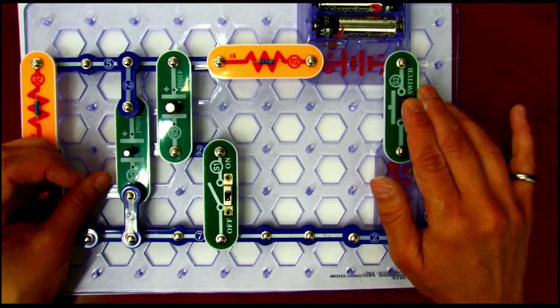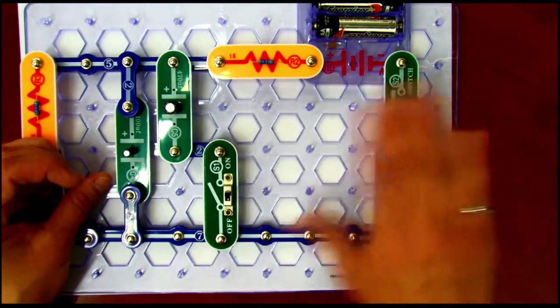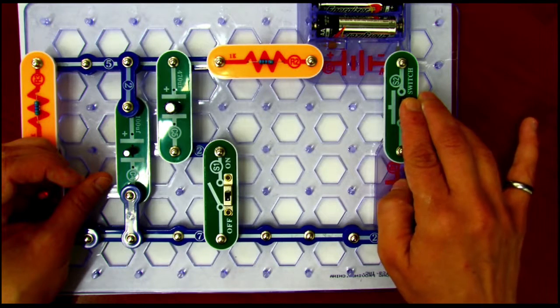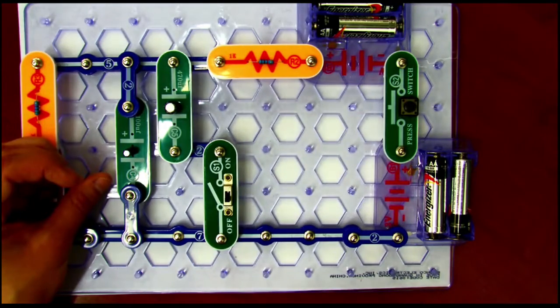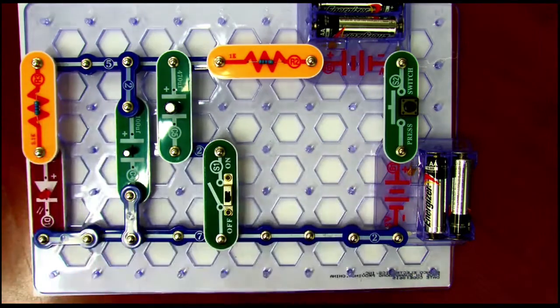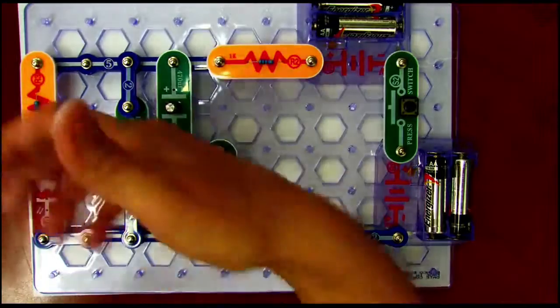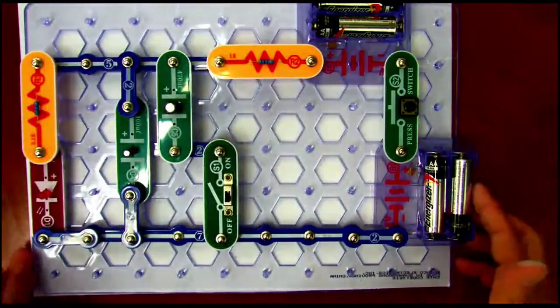We light them up. Now it takes a while for that light to go off. If I switch off that, here, I'll light them up all the way. Light them up. If I switch off that 470 microfarad capacitor, it'll much more quickly fade away. I'll pass this around, you can play with it, but with capacitors in parallel, if you're stacking up that energy in electric fields to use later on in devices when you're designing things for engineers, you want to stack them in parallel to get that added effect of them.